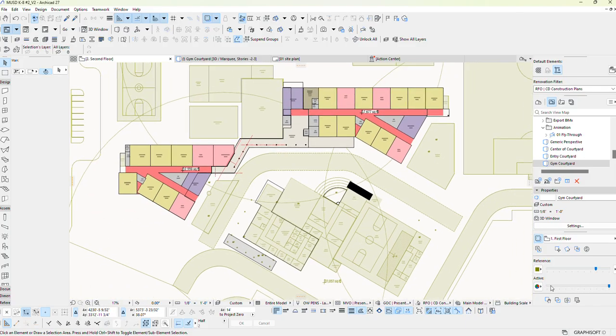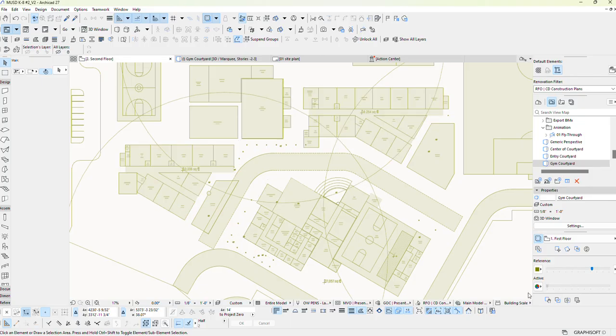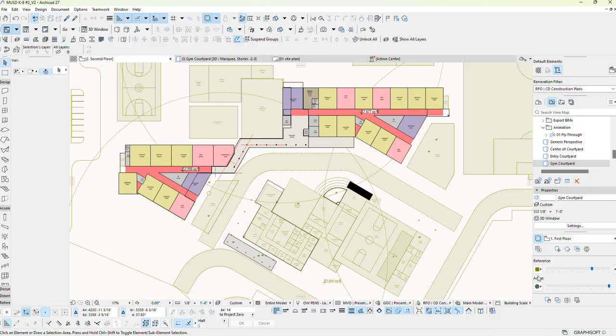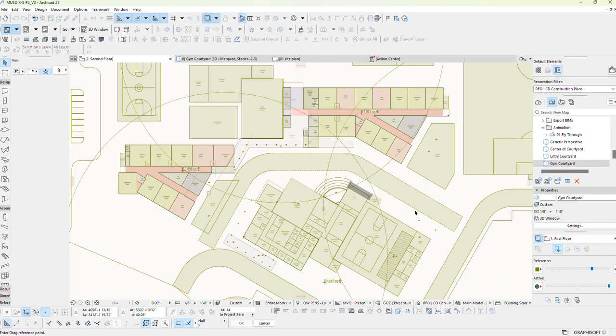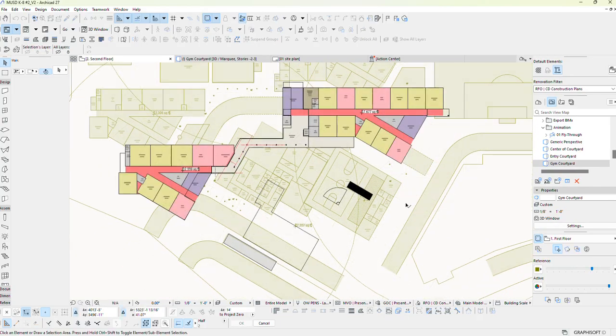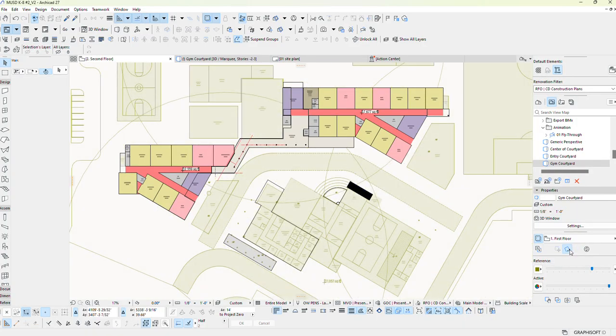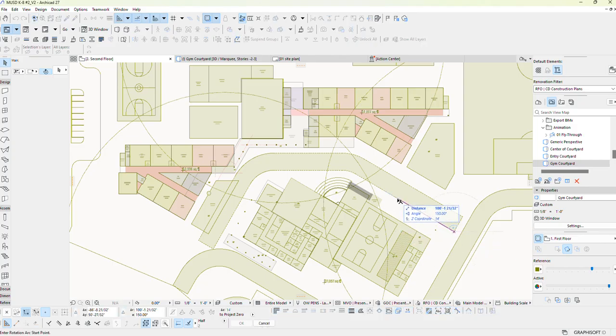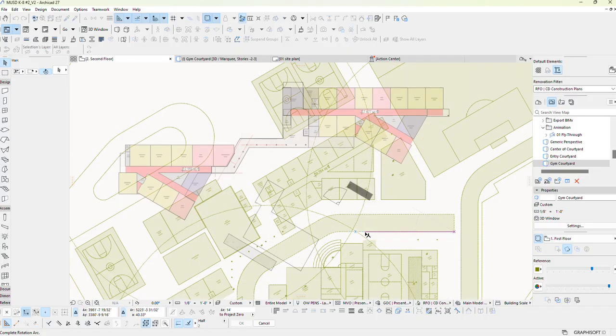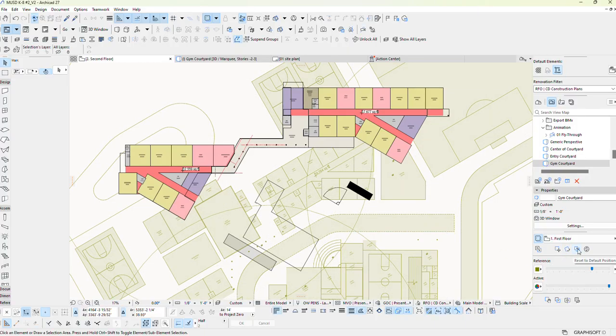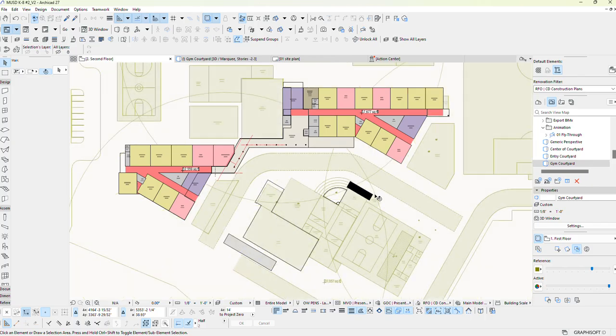We're like, well, I can do that in Revit. Oh, can you? Can you do that in Revit? Check this out. I can play with the opacity of the first floor, or this upper floor. I'm changing the opacity of the upper floor. I can move my underlayment if I want, and then just reset it back to where it was initially. I could rotate my underlayment trace paper if I wanted. I'm going to just set that back to where it was.